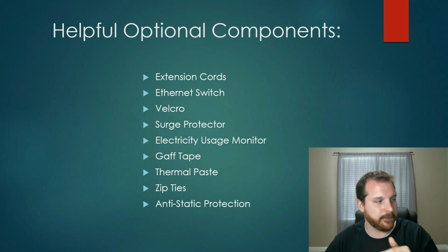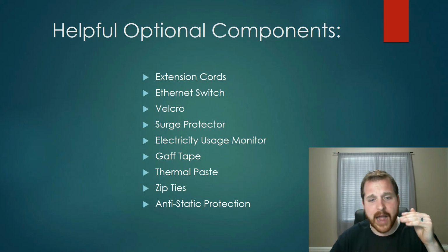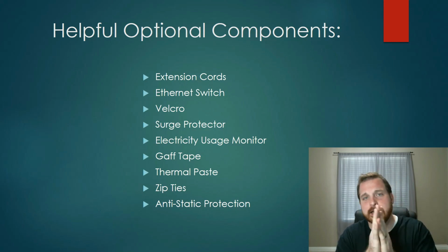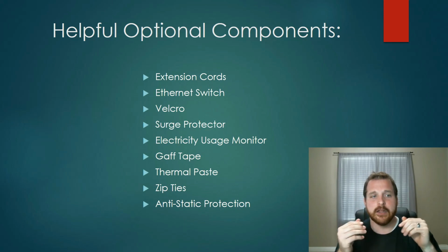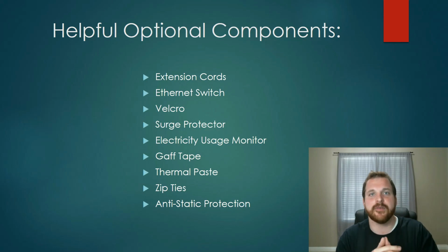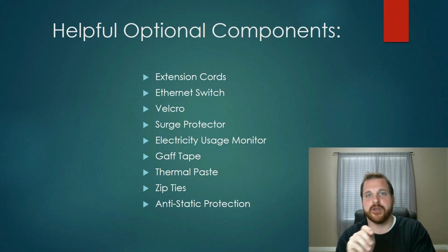And then anti-static protection. I tried a few different things. I tried the anti-static gloves, I tried the mat, and what I ultimately landed on that was least obtrusive and most helpful was just the anti-static wristband that you connect to a ground.